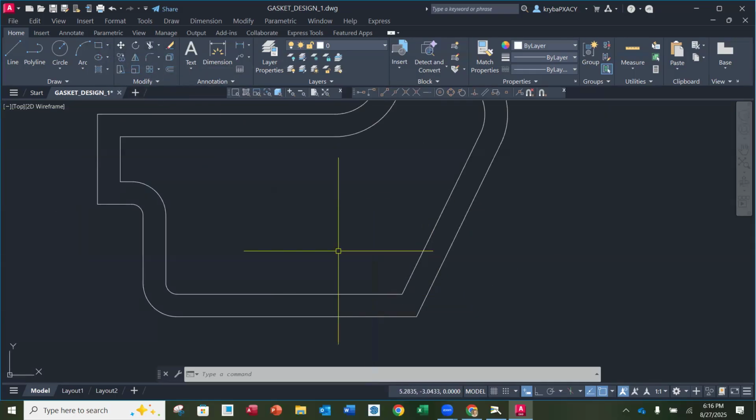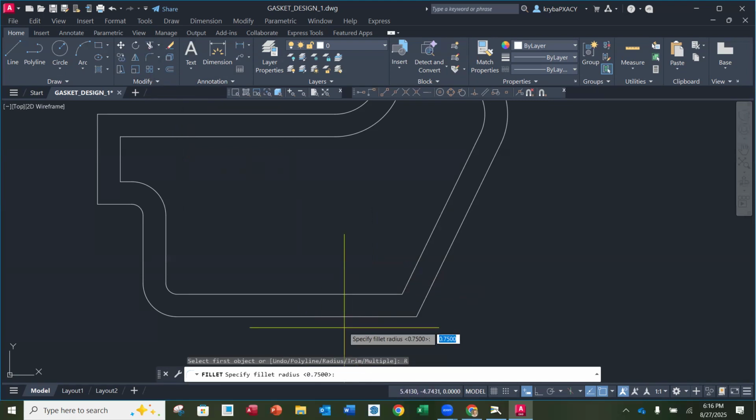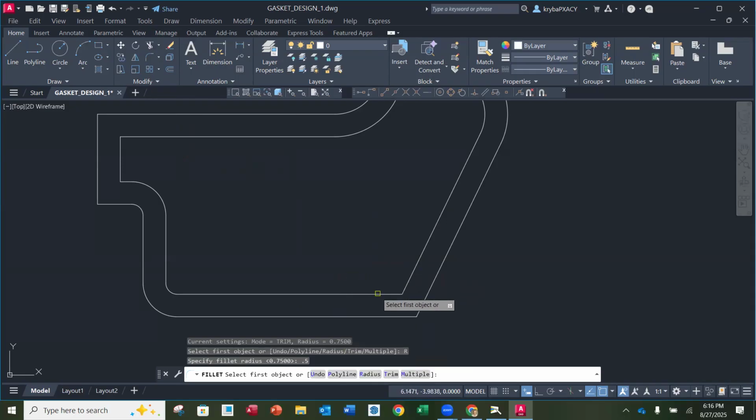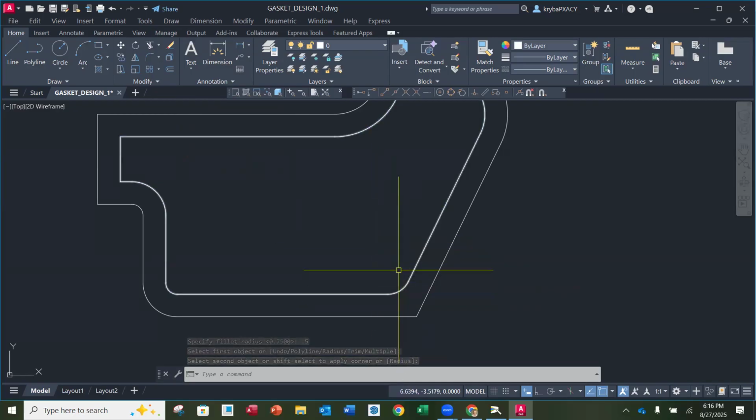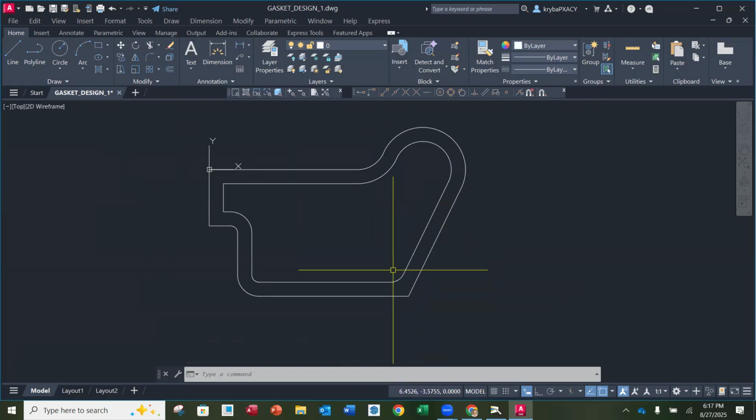Let me do this first because I forget if I can do this now or not. So yes, we have that one more fillet. It's going to let me. Okay, awesome. So I want this radius. It looks like it's 0.5, right? 0.5. And then I have to go here, and it's going to let me do it. I was a little concerned that it would say you can't do that on a polyline, but it'll let me. Good. So just add that one last radius. Thank you, Dominic. He's not here now, but thank you for calling that to our attention.